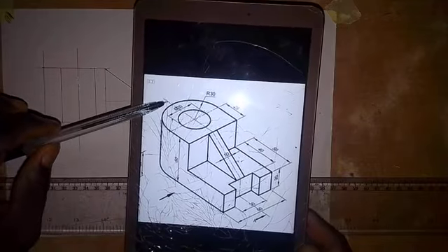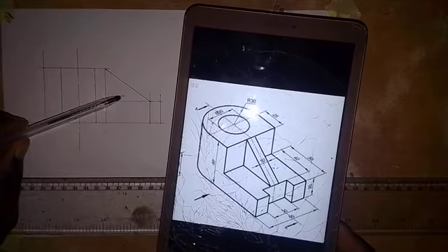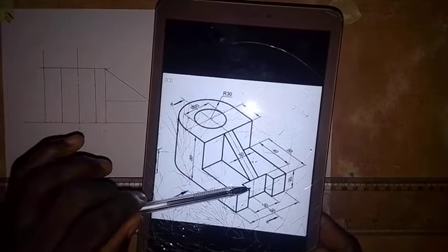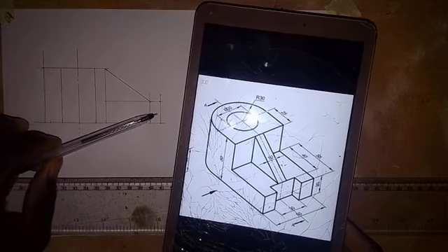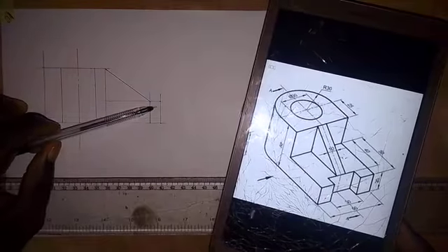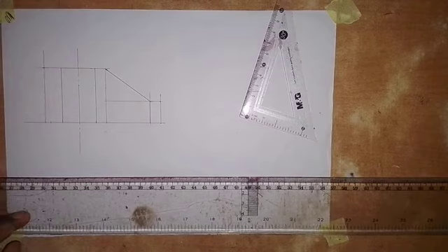As I said, when the cutting plane goes on the web like this, we leave this surface unhashed, and then this part from here, this part on this surface, will be hashed. So we are going to hash this. This surface will not be hashed because it is the rectangle that the cutting plane does not touch. Okay, so I want to bring out the visible outlines and edges of the object. Then we come and hash the surface together.